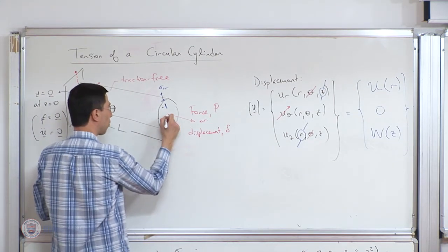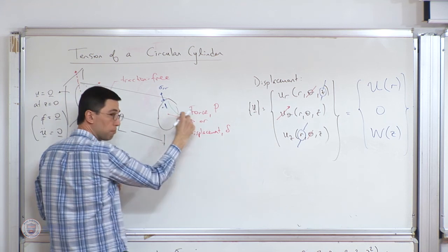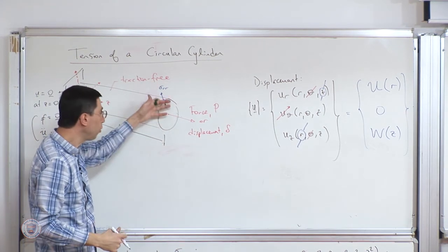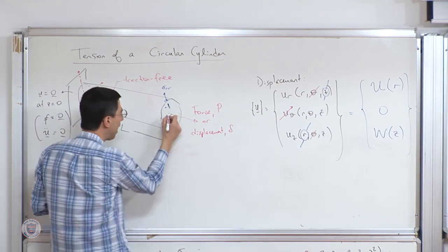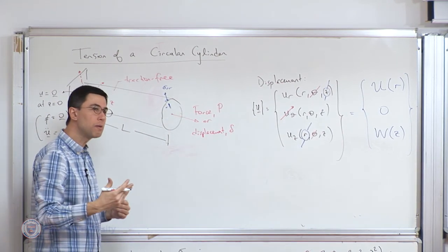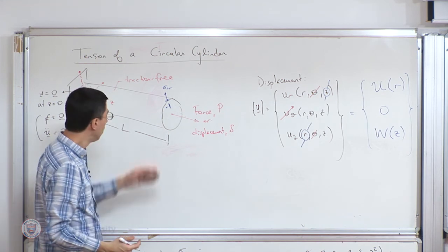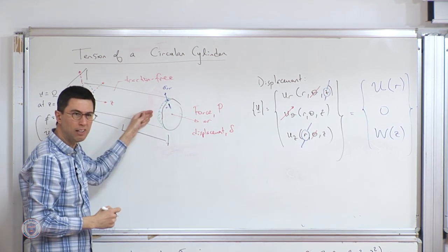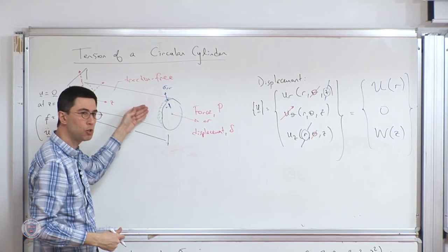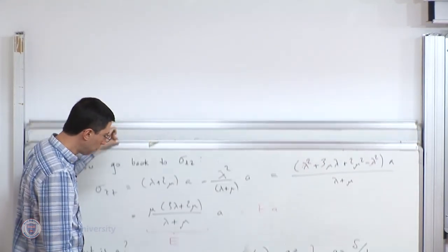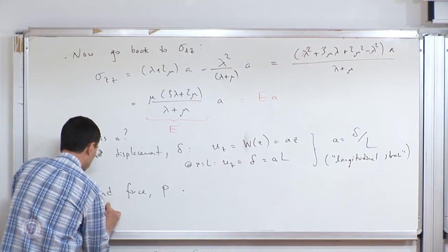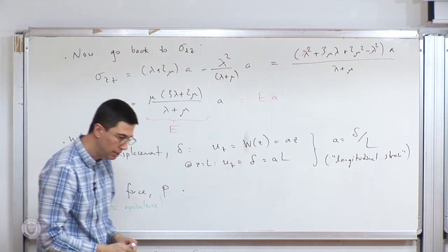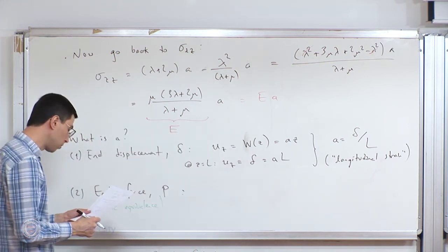If I indeed impose the force at a point, then there will be a very pointed displacement where I apply the force, right? Obviously, there would be an end effect. That could be how I'm applying the force on a very, very small area. And eventually, the argument is I don't care how I apply the force. If I'm sufficiently far away from this end where such end effects dominate, they probably decay exponentially anyway, to some situation where, for me, what is really important is that I have static equivalence. That's what I care about. So again, the underlying idea is we omit end effects or we invoke Saint-Venant's Principle.